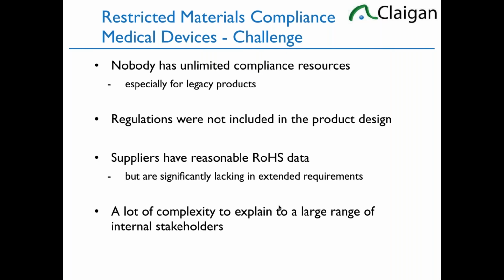As it moves to more custom components, the different pieces that you design by drawing and you specify, and you're not buying off the shelf, as more and more compliance requirements go to those, the contract manufacturers or fabricators do not have the compliance data for your custom parts. So as a lot of the compliance requirements start shifting more to custom parts and away from the circuit board, data gathering, especially with the extended requirements, is not very fruitful. There is huge value in specifying up front what you need the product to be compliant to and working with suppliers, but gathering data after the fact is usually not very fruitful, especially beyond RoHS.